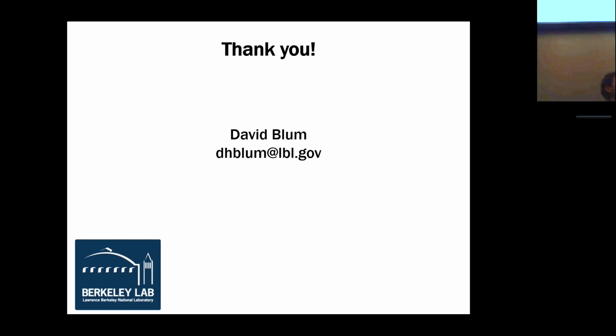in our current test cases, either how the Buildings library implements the heat balance method of the room, or the IDEAS library, which are 2 libraries that extend the Modelica IBPSA library. So basically full heat balance, including floor constructions, wall constructions, things like that. There's also an opportunity, and we're working on this as well, to include room models from Spawn of EnergyPlus. So there we would basically use the EnergyPlus envelope model and incorporate that. So from a modeling perspective, those are the methods that are implemented.